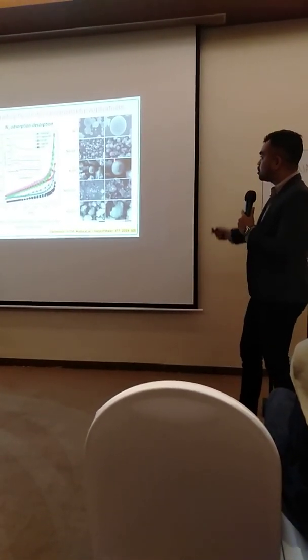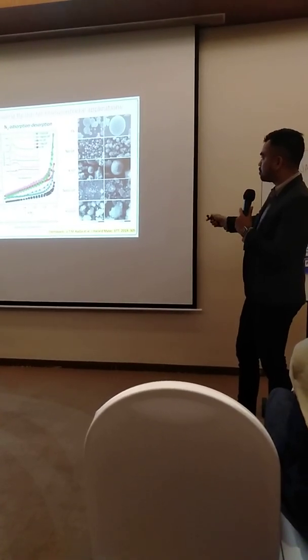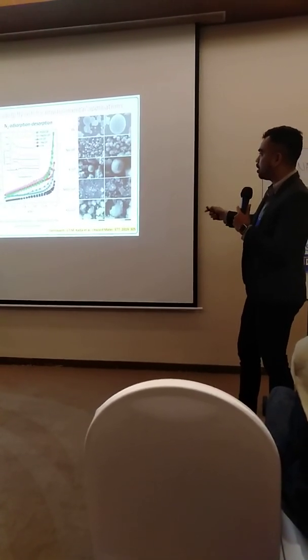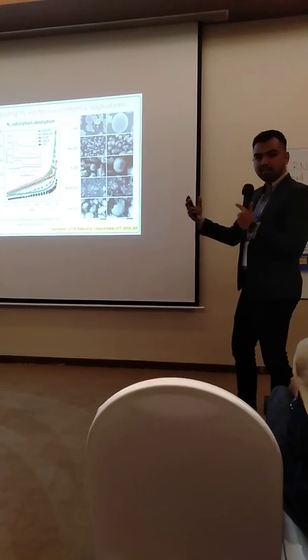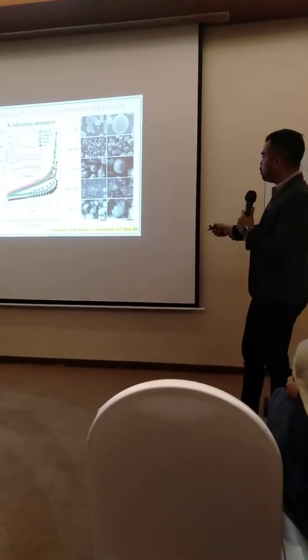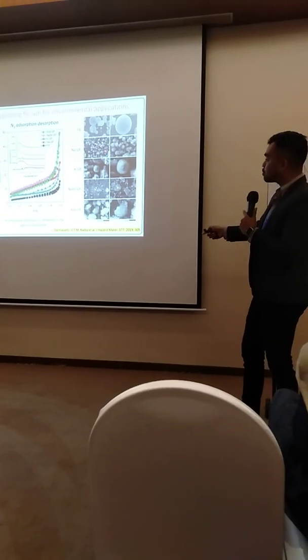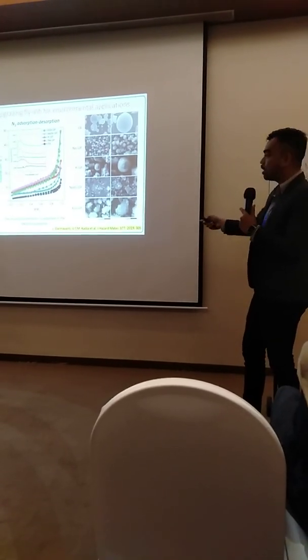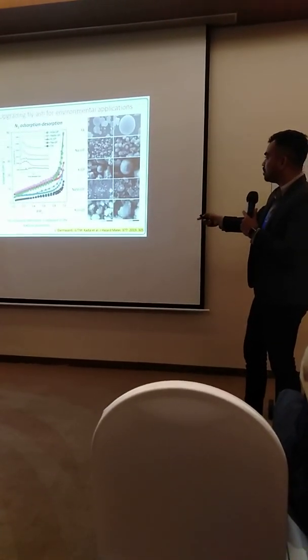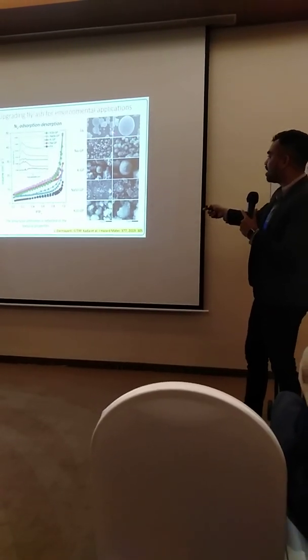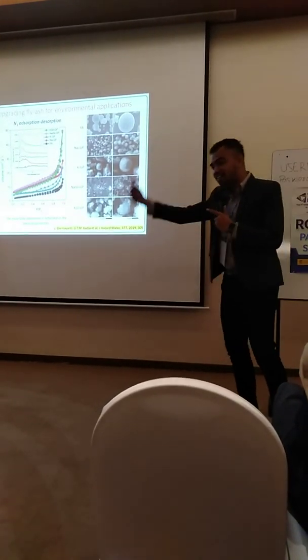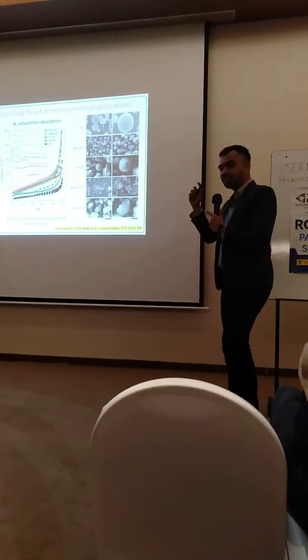samples. And also you see in the electron microscopy, this is fly ash, very big particles. But when you use sodium, the size is decreased, as well as with potassium. But you see, sodium decreases the size of fly ash to a further extent than potassium.